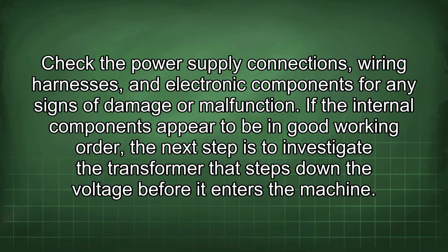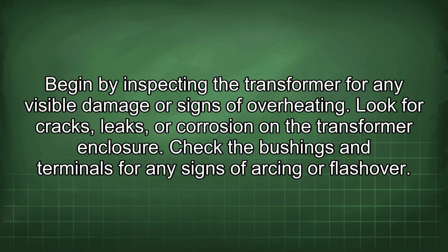If the internal components appear to be in good working order, the next step is to investigate the transformer that steps down the voltage before it enters the machine. Begin by inspecting the transformer for any visible damage or signs of overheating.